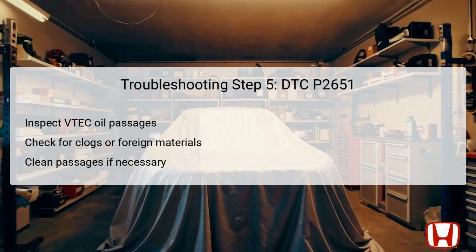If you discover any debris in the oil passages, it's important to clean them thoroughly to restore appropriate oil flow. This not only ensures the rocker arms receive enough lubrication, but also enhances the VTEC system's performance. Keeping these passages clean is vital to prevent recurring trouble codes and protect engine integrity.